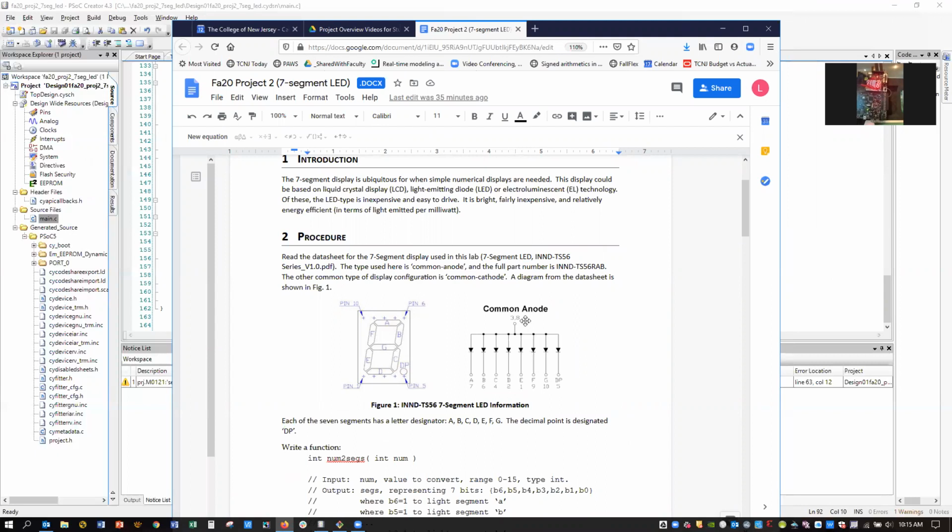And you will wire the anode to the supply voltage, which you want to be 5 volts in this case, and you're going to wire each cathode to a general purpose input-output, a digital output pin, through a 330 ohm resistor, and you should be able to do some figuring out about things there in terms of what the current will be and such.